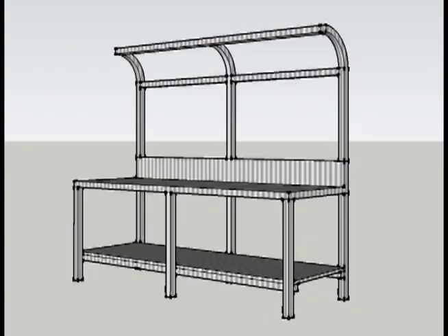When creating custom components for a BIM model, the user may prefer to use Google SketchUp to model the component instead of the conceptual mass creator in Revit. However, trying to load a SketchUp file directly into Revit usually causes errors or system crashes. This tutorial will explain the procedure for importing a SketchUp model into Revit without experiencing these frustrations.